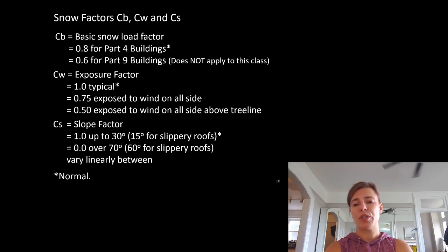This always begs the question, and I always see people making this bold move that they're going to make a super steep roof to get rid of snow. That makes sense in places that we have high snow. Toronto has snow, but it isn't as high as some other regions. We end up with about, in Toronto, 1.12 kPa of snow. We're going to do that calculation, don't worry about it. Places like Ottawa are somewhere in the region of 2 or higher.